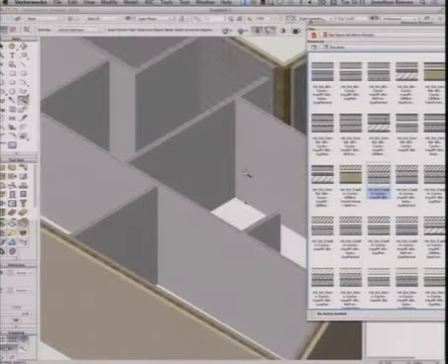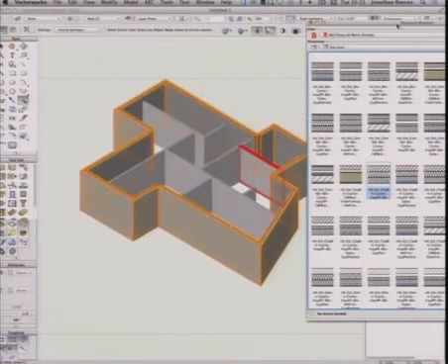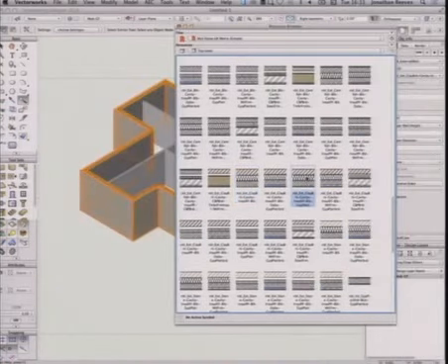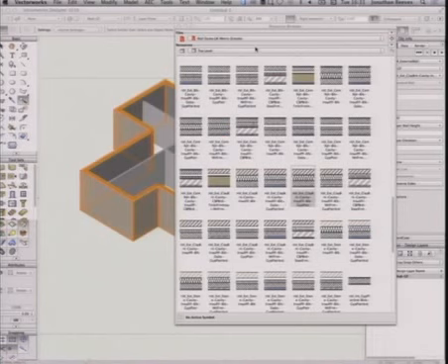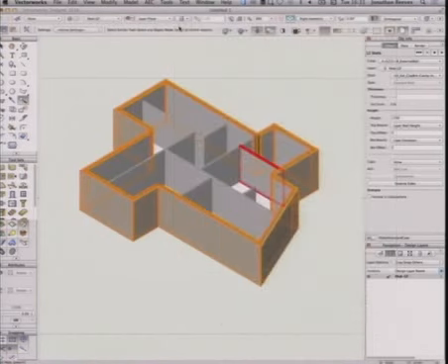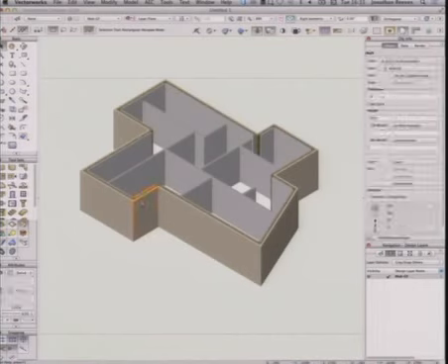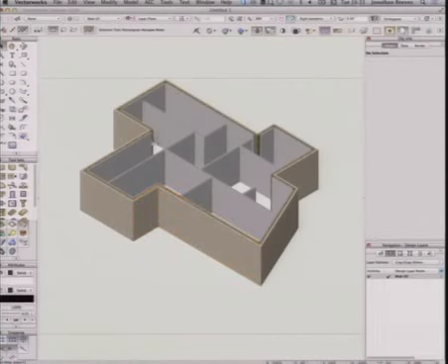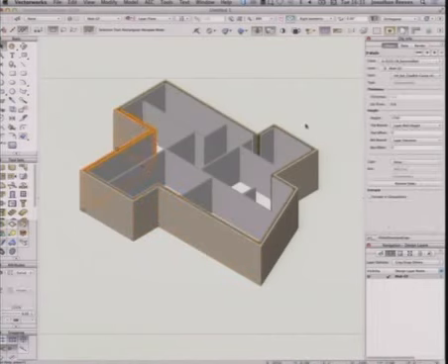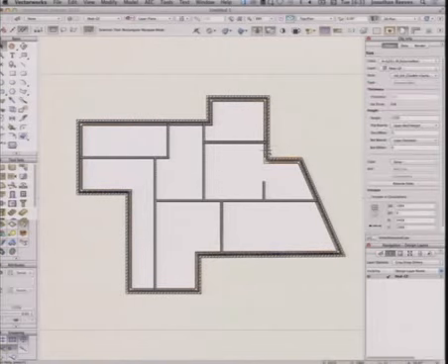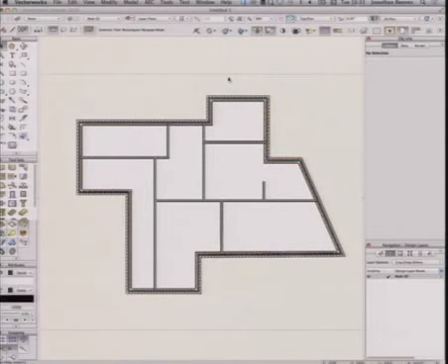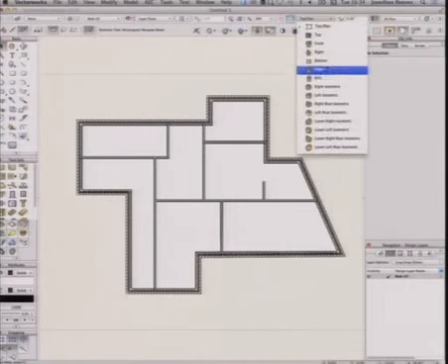So you can see I've immediately replaced those walls with something a little bit more cheerful, possibly. Let's see if we've got a nicer brick in there. But the beauty is it's extremely fast. I can replace them at any time in the project, and it's something that I can kind of keep doing to my heart's content, really. So sometimes you have to repair a few joins, depending on how you've done it and whether you had auto join on. Overall, a relatively satisfying and quite a quick effect from generating those walls.